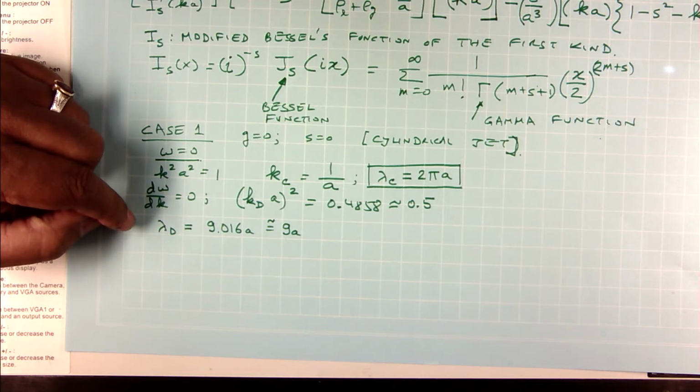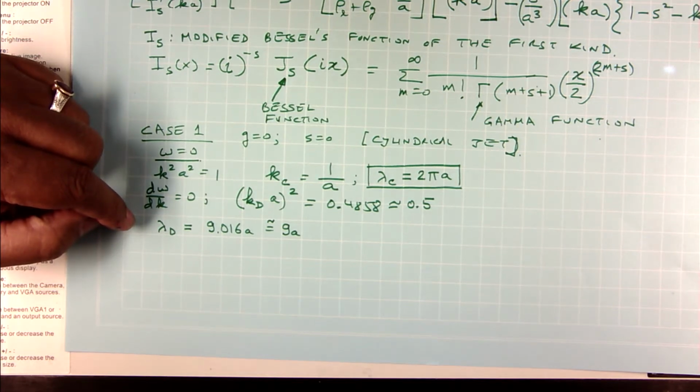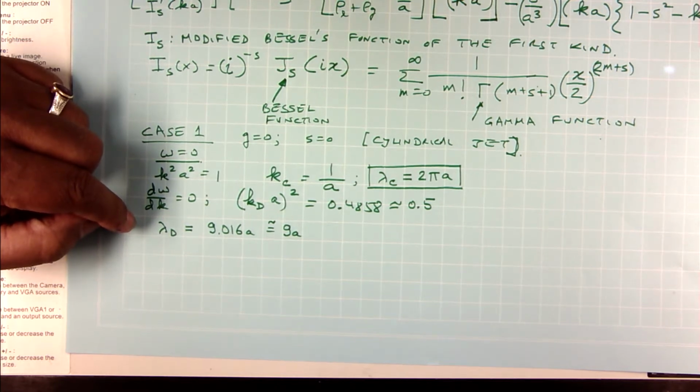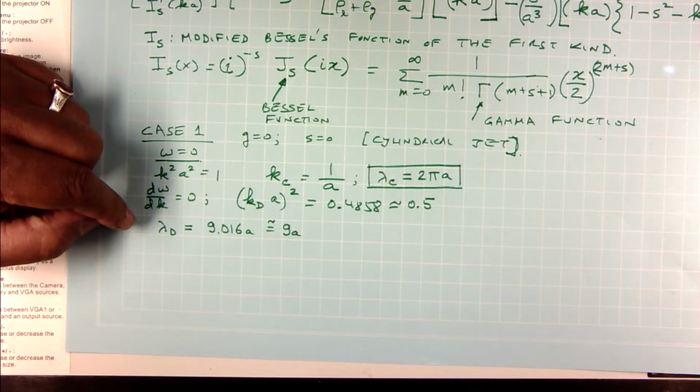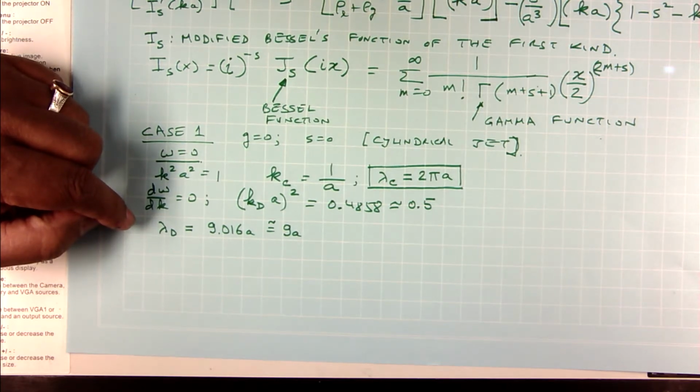But if you do a really tiny amount of flow rate, that you have a very thin stream coming out, that is more likely to break up into droplets in the amount of distance you have from the faucet to the bottom of the sink or the top of the sink. So, you will see that as you keep reducing the flow rate in your faucet, at some point it will start breaking up into individual droplets. Now, the question is, how far does the jet have to travel in order for that first droplet to form? We will come to that in a minute.